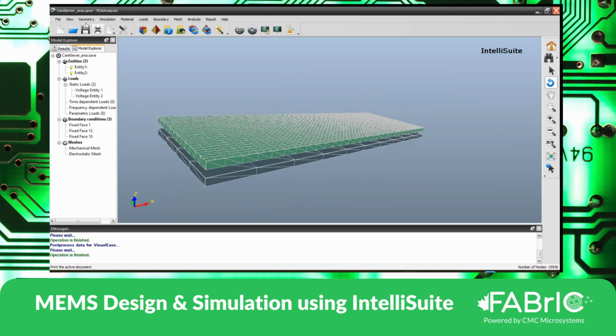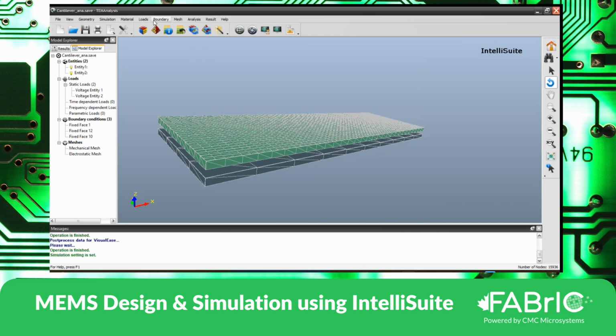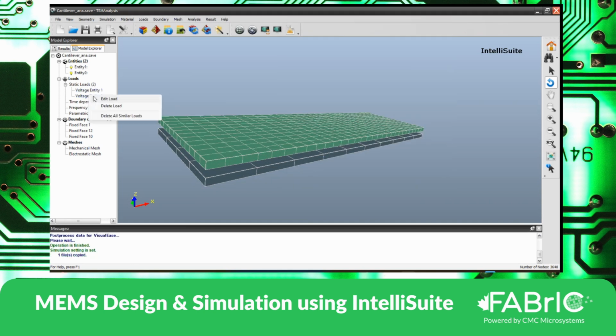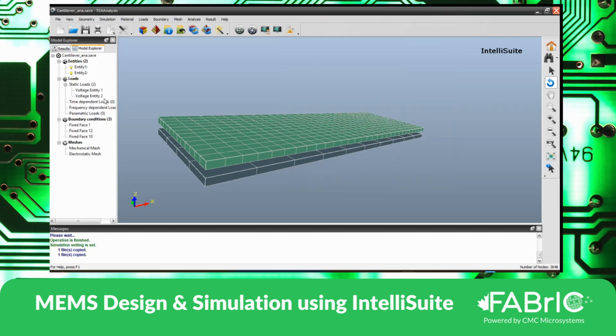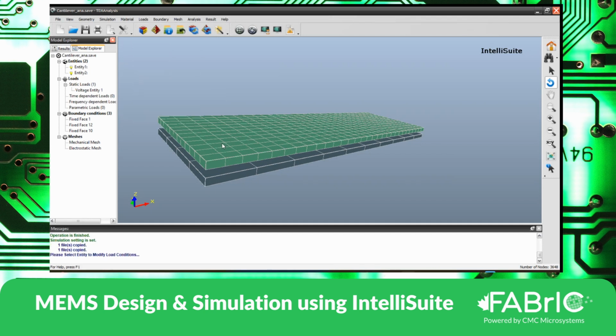Now, the one common simulation that we see with electrostatic or electromechanical based simulation is a pull-in voltage extraction. Okay, so pull-in voltage extraction. Instead of applying a fixed voltage, I need to apply, probably I'll delete this and then freshly apply voltage entity on the top.